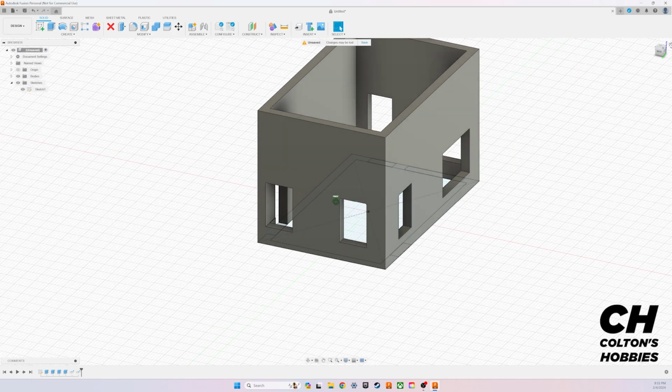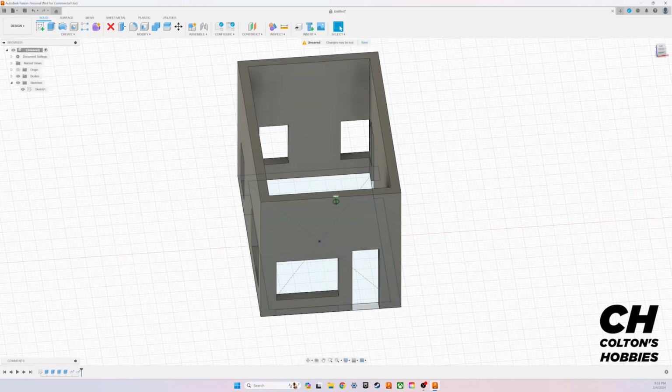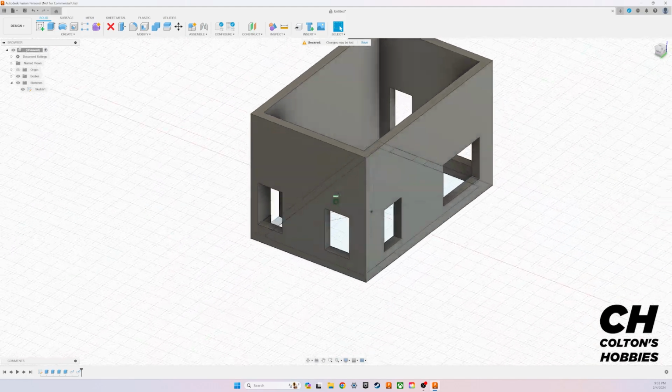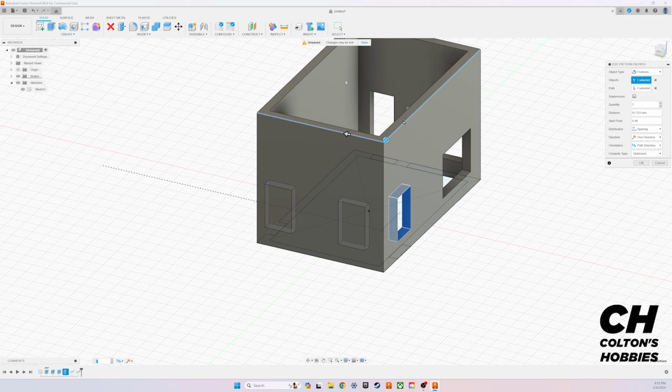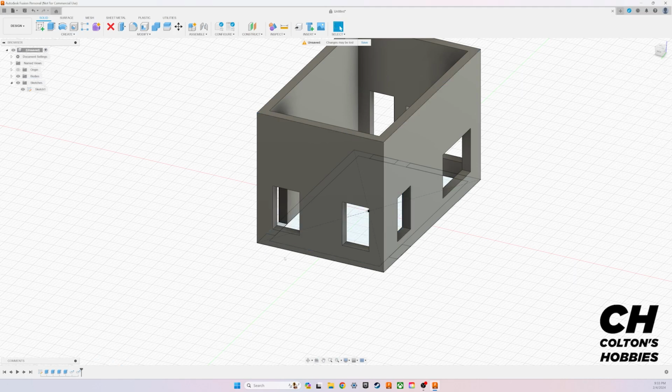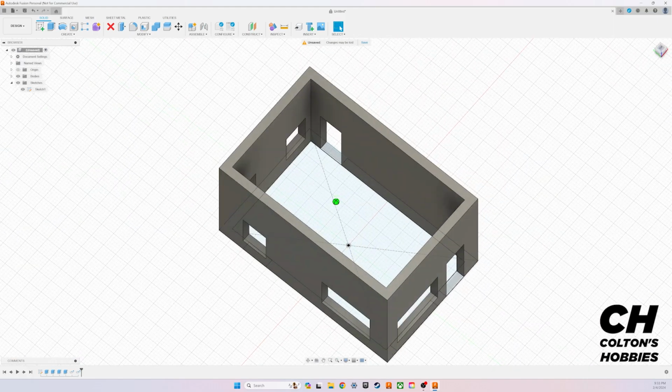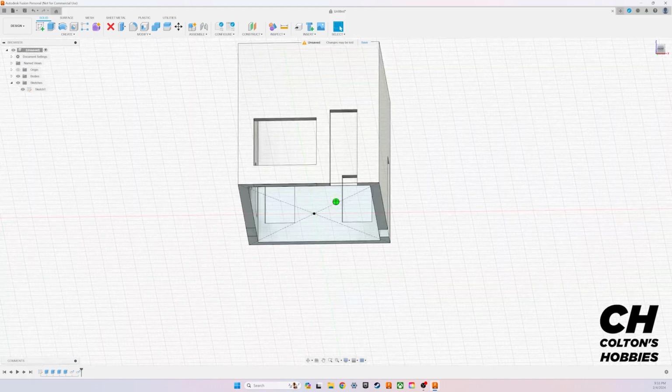Not the best placement, but it works. So for, it actually kind of cuts into that corner, doesn't it? I don't like that. So let's go back, and that's the great part about parametric, is that we can go back in timeline and fix things. So bring that back towards the middle, hit OK. There we go. Nothing's cutting off. The 3D file looks good.